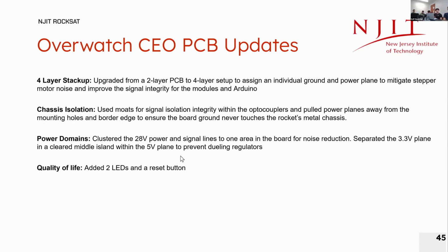So for the Overwatch CEO PCB updates, I've upgraded the PCB to a 4-layer stack-up so that I can assign an individual ground and power plane to mitigate the stepper motor noise and improve the signal integrity for the modules and the Arduino. I have the chassis isolation, so I use moats for the signal isolation integrity within the optocouplers and pulled the power planes away from the mounting holes and border edge, just to make sure the board ground never touches the rocket's metal chassis.